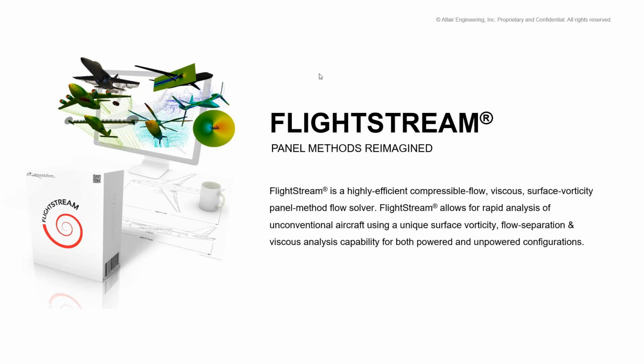This is all done to enable aircraft design people to make design decisions in the early design stages. The key advantage of FlightStream is that even though it's a computational method, it works directly on the surface mesh, so there is no volume mesh required. It is not a meshless method per se, but we are talking about the surface mesh only. That makes the tool very lightweight. We are talking about seconds to minutes of runtime. You can run it on single workstations and laptops, and you can scale it to HPC, but for distributed memory parallelization rather than shared memory parallelization for the given simulation.